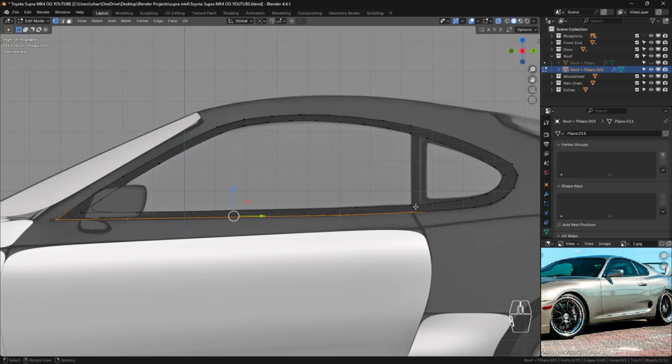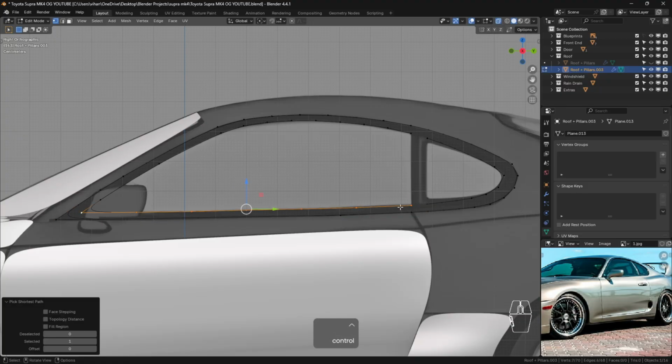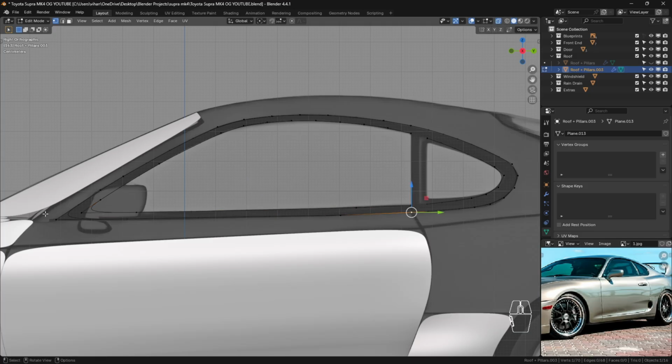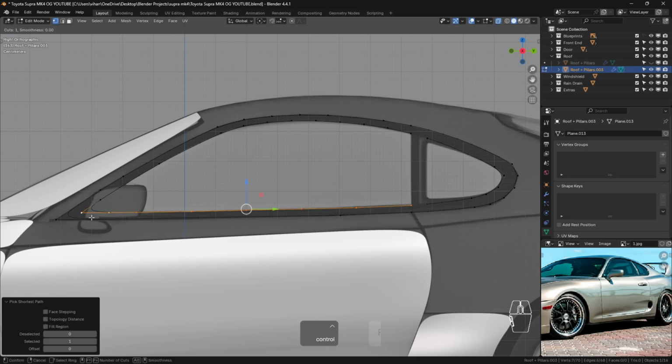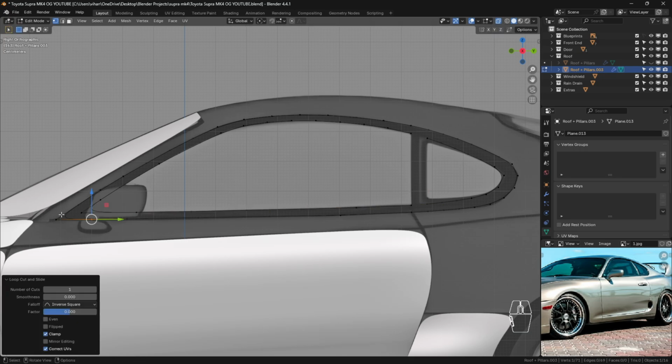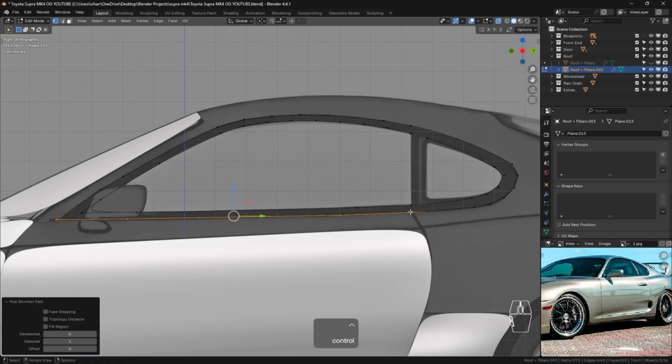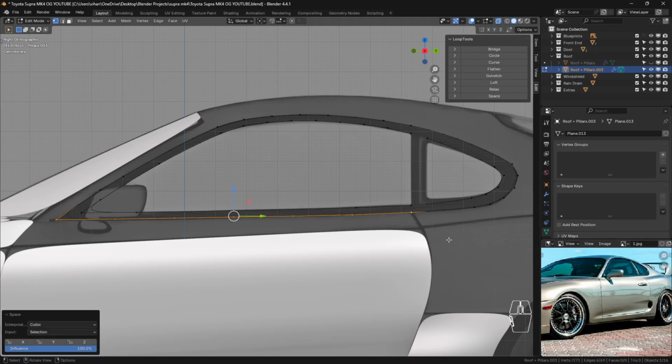Now press Tab. Now let's just go ahead and make sure the vertex count right here is gonna be the same. Alright. Just select. So we have a vertex less here. We have maybe 7 up here. So just go ahead, Ctrl R and add one here, and then we'll just space it out again, right? Just space it out again. That's perfect.